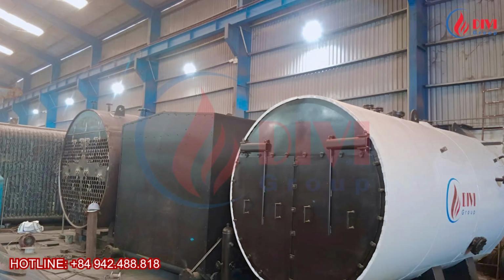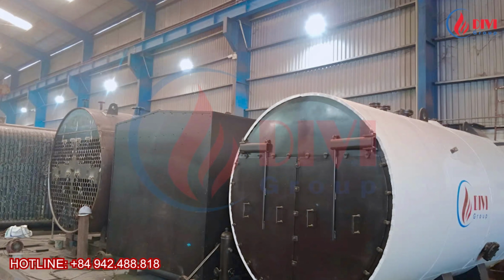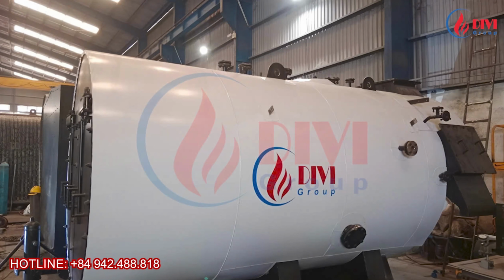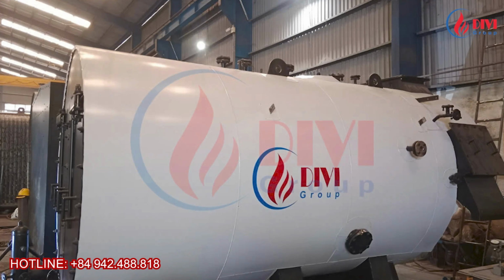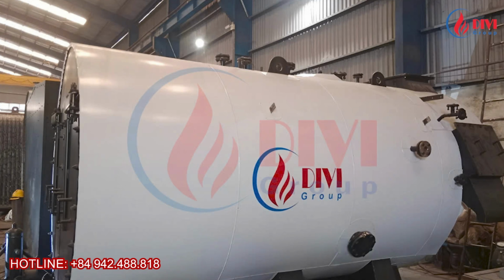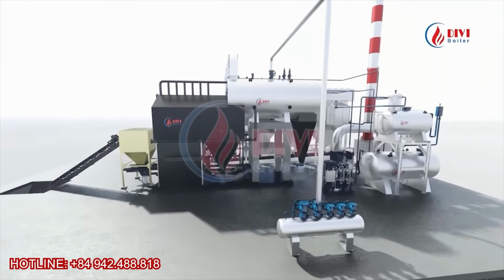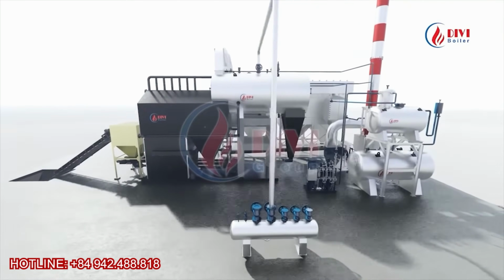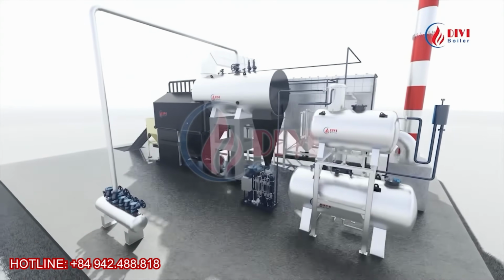In a combined water tube and fire tube boiler, the steam drum is not directly exposed to the flame. This type of boiler is commonly designed for capacities of up to about 20 tons of steam per hour. Its typical design pressure is generally up to around 16 bar. For higher pressure applications, material and manufacturing costs increase significantly, making this design less economical than some other boiler types.